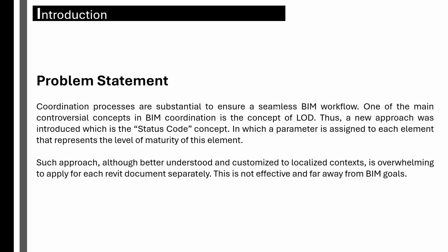First of all, coordination is very substantial. It is of utmost importance in BIM workflow. So in order to enhance this coordination, a lot of concepts are there, such as the LOD or the level of development. However, they are very controversial and very complex. Some new approaches are called, one of them is called the status code concept, in which a parameter is assigned to each element in the model that represents the level of maturity of this exact element.